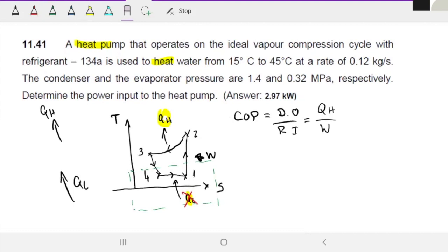And the next thing is over here. Check this out. Ideal vapor compression cycle. With that said, if it's an ideal, you guys want to write this down. If it's an ideal cycle, there's a couple of things that we know that will happen. First up, when we go from state 1 to state 2, we know there's no creation of entropy, right? It's a completely reversible change in state, right? So this guy shoots straight up here from 1 to 2.